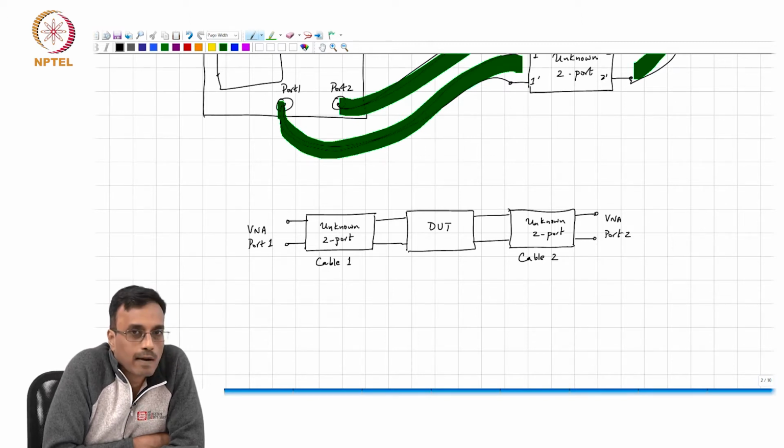Yes, Karthi, what do you think? We need a frequency, we need obviously a sine wave generator, right? If you wanted to make measurements fast, you probably need two of them, one exciting port 1 and the other exciting port 2, or you finish making measurements at port 1 and then switch to port 2. What you are measuring at port 1 are the transmitted and reflected waves, and likewise at port 2 the forward and backward waves, and you can control which source you want to activate.